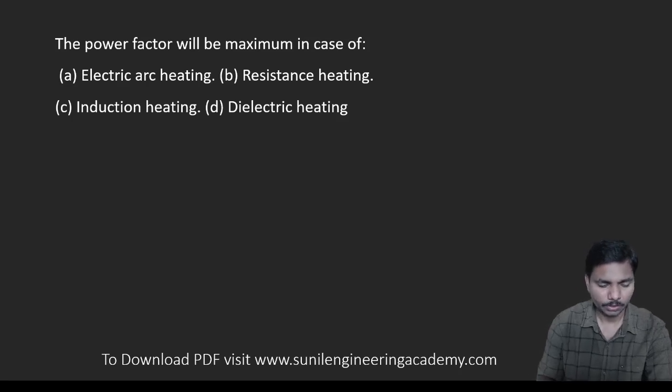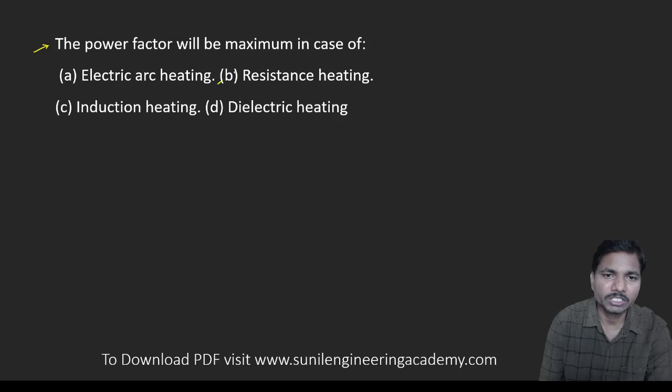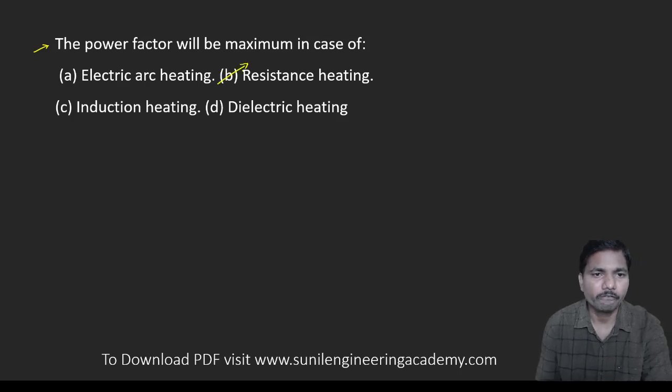Coming to the first question, the power factor will be maximum in case of dash. When we will get the maximum power factor? Whenever voltage and current are in phase. This will happen in case of pure resistance. So in case of resistance heating, there is a chance of maximum power factor.